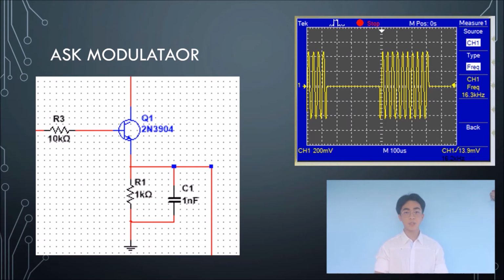And lastly, I used a transistor as my ASK modulator. My ASK modulator transistor is a 2N3904, which produces my ASK modulated signal. My modulator accepts the signal directly from my sine wave oscillator to its collector, and then the binary signal from my square wave oscillator to its base, and lastly, its emitter is connected to the ground. Before it's connected to the ground, it has a parallel 1 kilo ohm resistor and 1 nanofarad capacitor. My ASK modulated signal is collected or read from my emitter.